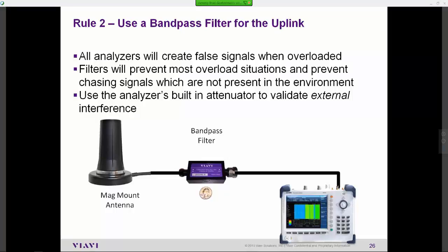You can also see degradation in signal quality when you're doing signal analysis on our instrument if you've in fact overdriven our instrument and you've not used not only a 40 dB down test point, but oftentimes added about 25 or 30 dB of internal attenuation when looking at your transmit signal quality.